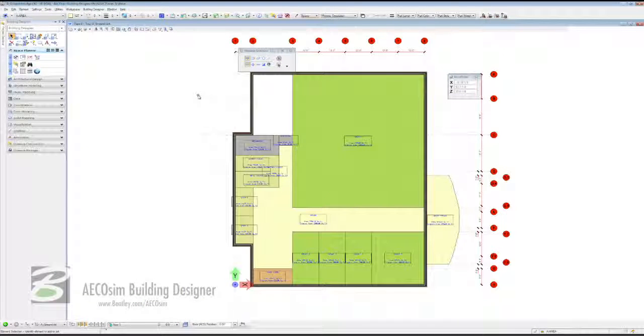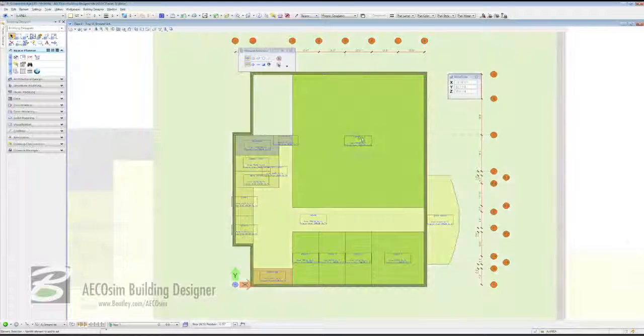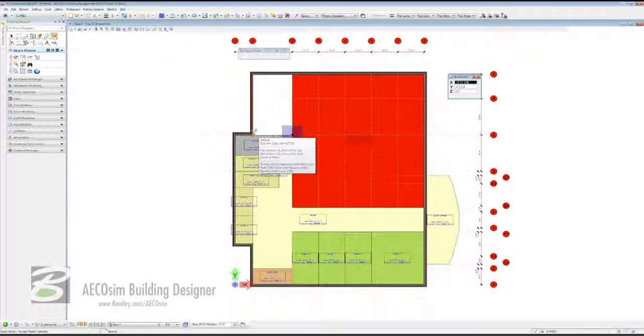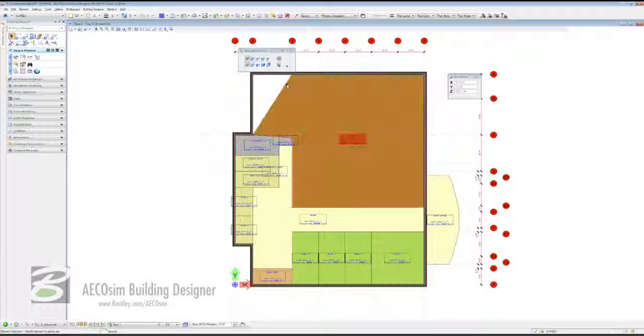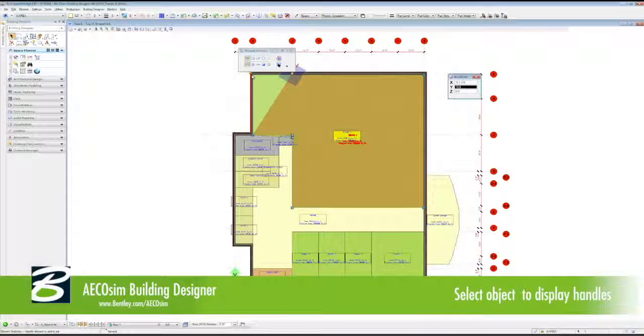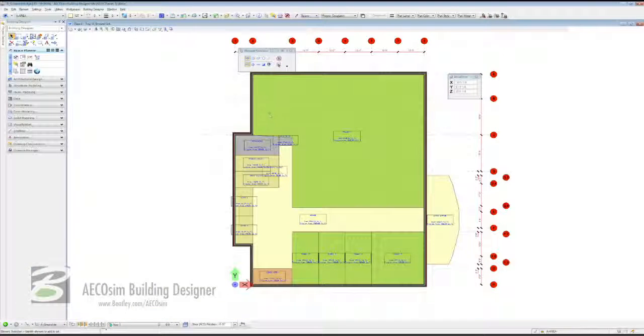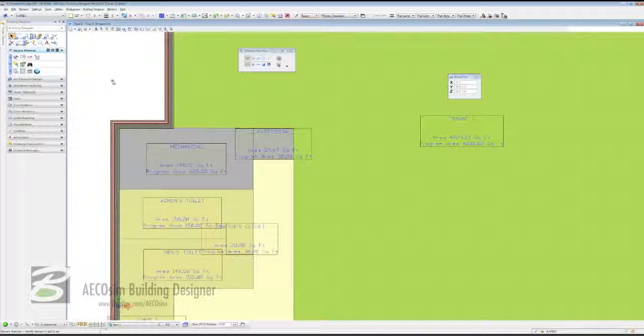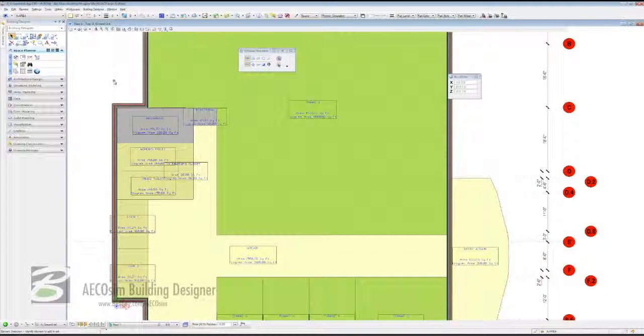So here are all of our spaces laid out, and the one thing that we have to do now is stretch that largest tenant 1 to fit the corner area to its left hand side. To do that, we insert a vertex, and to do that we come to our task-based interface, to our modify tool sets, and we come down here and say insert vertex. We can quite simply select a vertex, insert it here, and then to complete it, we can select it and bring across via our Windows handles our other point and tidy it up too. And as we do so, all of the time, our area and our program area are constantly adjusting to the actual finessing points that we're placing on.